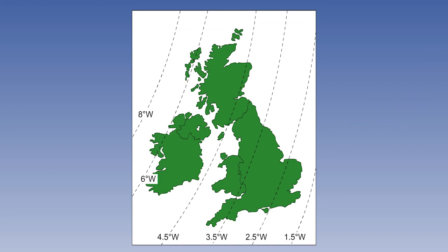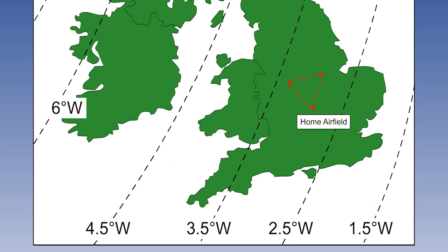Now let us see how we would use a magnetic compass to steer a true heading as the variation changes, and then we will see that much the same principles can be applied to steering a grid heading. This short triangular navigation exercise, which is typical of a PPL training route, all takes place between 2 isogonals. We use 3 degrees variation for the whole route.